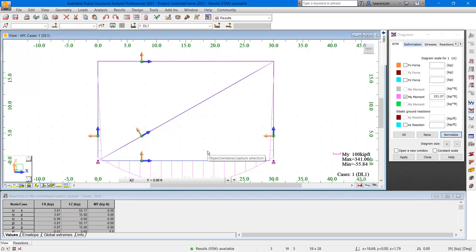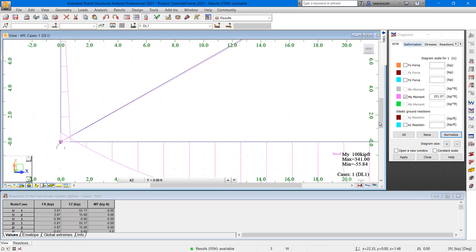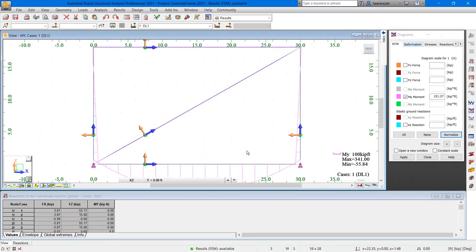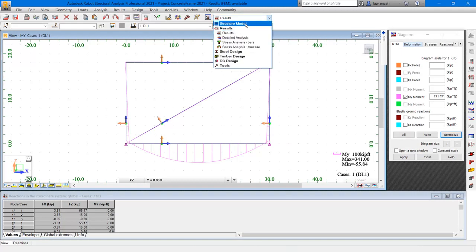From the results, you can see that we have a simply supported beam. When we inspect the start and end of the beam, we can see that we have some fixity. This is due to the interplay with the moments. To simplify the results on the beam, we will go back to the start layout and change the release conditions of our beam. On the standard toolbar, select the Layouts pull down, then select Structural Model, and then pick Start.